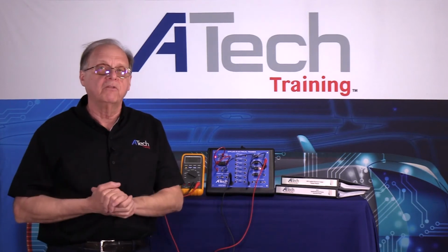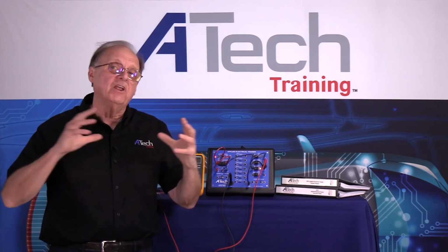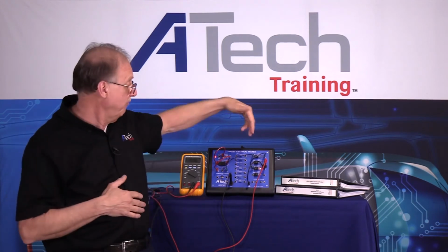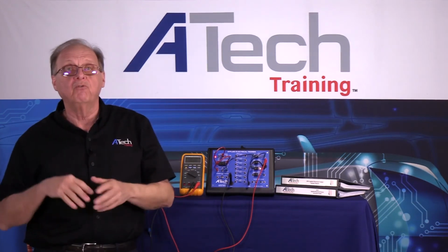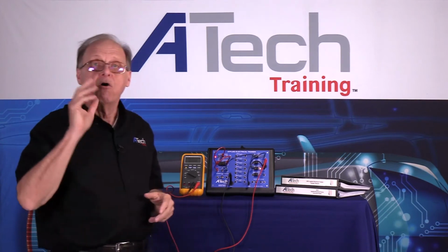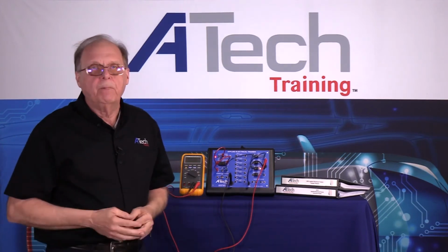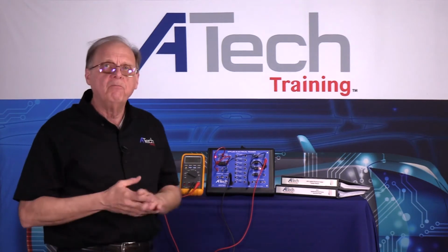And you have to look at the series circuit as it goes across, and find an issue on whatever the problem is. Biggest thing about it is this is where you would be able to do testing on it and getting that across. Voltage drop will be their friend. If I would ohm these out, there's an issue up here. If I ohm these out, what happens?